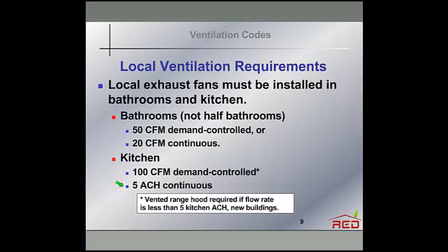And of course, if you have a gas range, you have the potential of carbon monoxide, which you might think you don't have the potential of from an electric range, but there are times that an electric range will give off significant levels of carbon monoxide. For example, when you're cleaning the oven with the self-cleaning feature. I have measured in my own kitchen up to 250 parts per million of carbon monoxide when an electric oven is in cleaning mode.